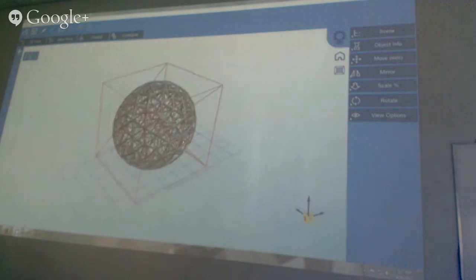Here's a question. If you're going to be printing at 50 micron resolution, does that also mean that at some step you're going to have to adjust the distance of the projector from the vat? Yes. Sorry to jump in. We make sure the projected area size on top of the vat, the bottom of the vat, has to match that.